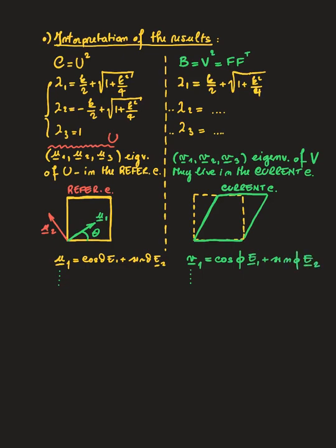And if you at this point draw these vectors in this configuration, you discover something, and in particular you discover that the vector v1 is not, as one would expect, aligned with the diagonal. In other words, if this is the diagonal of this deformed parallelepiped, and this angle, for example, is equal to alpha, then what you can find is that the angle corresponding to the most stretched fiber is not alpha.